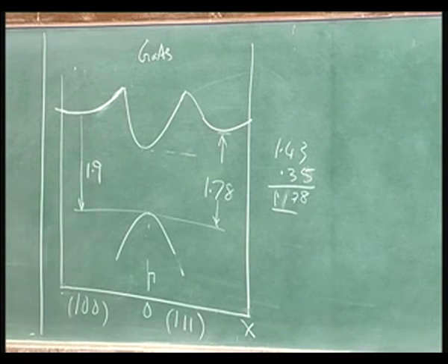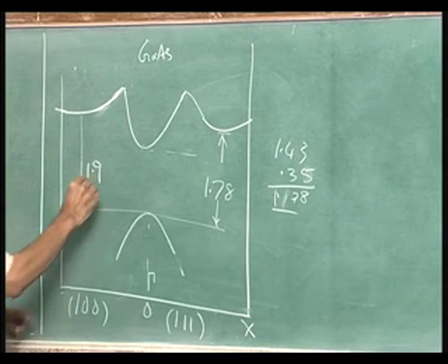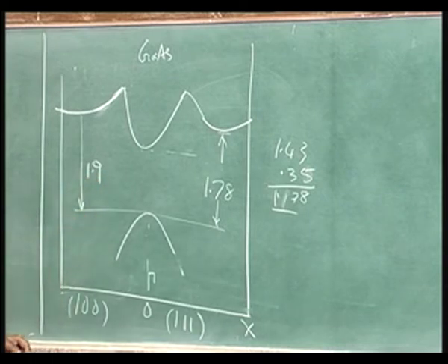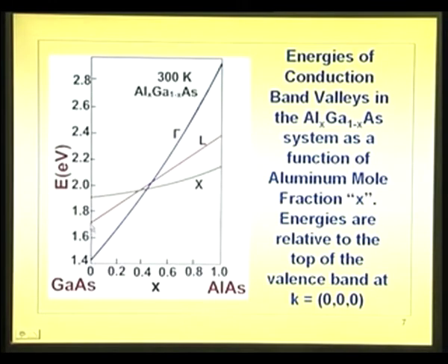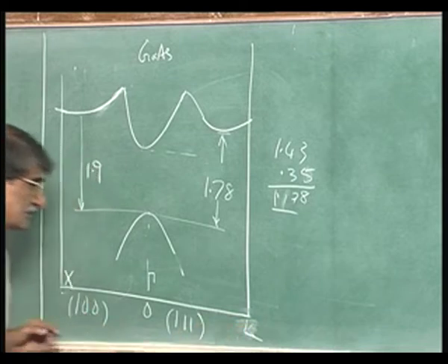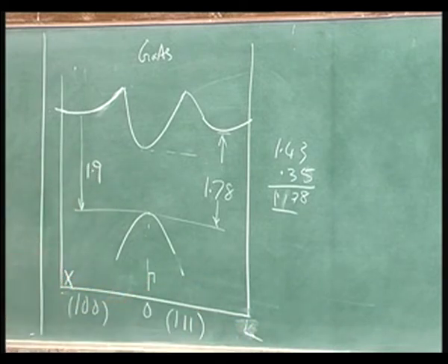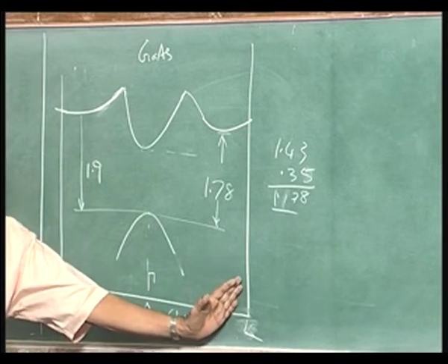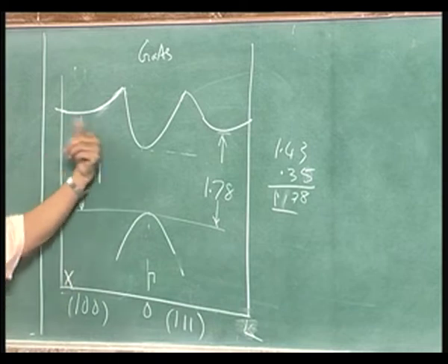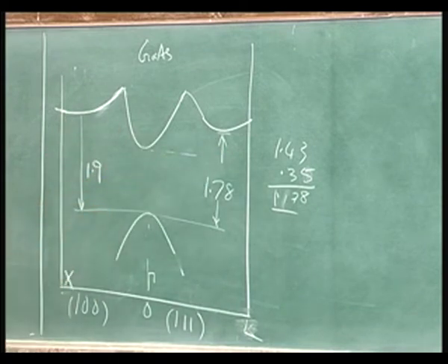See, we were drawing some effective thing earlier with the linear line. So, now this is called the x. If you see the diagram here, this is the direct band gap at 1.7 something, and this is about 1.9 or so. So, this is x and this is L. This shows the boundary of the, it is called a Brillouin zone actually, let me not say that, because it is the boundary of that region where we are plotting this. That is L, this is x. There are 2 values near that portion. If you take aluminum arsenide also, you have similar structures.